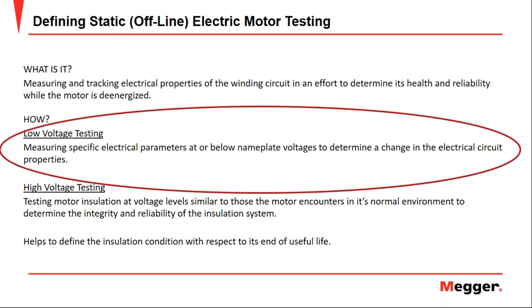However, in order to have an effective diagnosis of the insulation system, they both must be performed. Low voltage tests are pass or fail tests, but the high voltage tests are the tests that give predictive indication and allow me to have a clear scenario of the motor insulation condition, as we will see a little later.